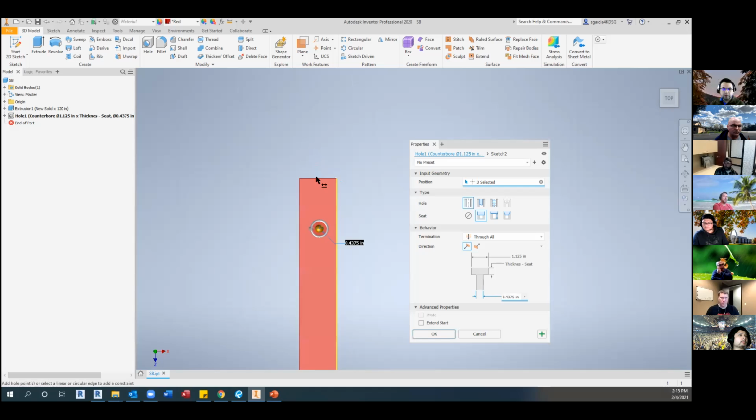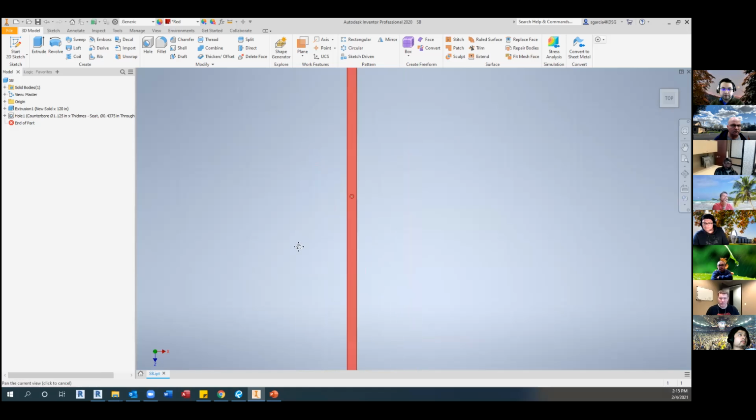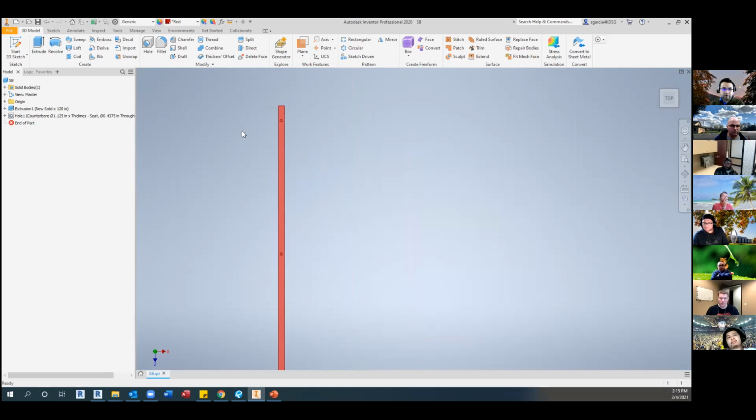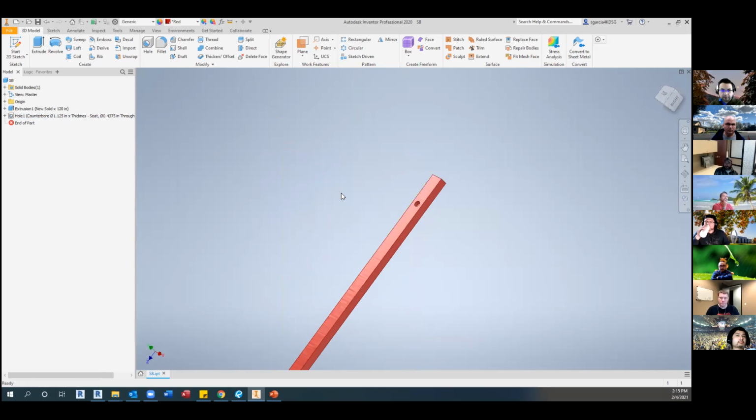And the final hole is here, and this hole is exactly the same logic. This, the start. And from here to here, it's going to be the same logic as we already discussed to be in the center line. So width divided by 2. Okay, there you go. So I have 3 holes. Every time I change my part, those holes are going to be adjusted by the logic that I already created. So let me hit save, and there you go.